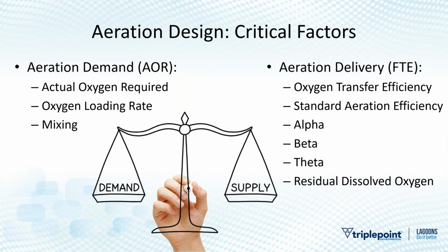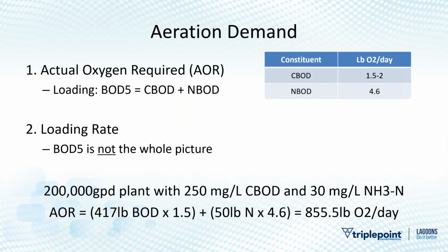So meeting that demand is pretty important, but you don't necessarily want to supply more than those bacteria require, because if you do, you're just burning up cash to do nothing at a certain point. Unless you're trying to increase mixing, putting more air will raise the DO, but not do a whole lot for your system. So it's kind of a delicate balance you want to chase here.